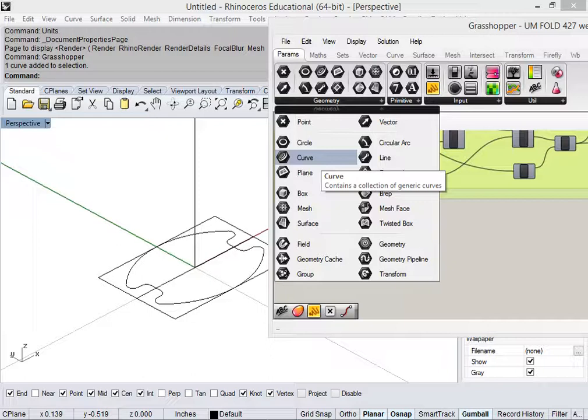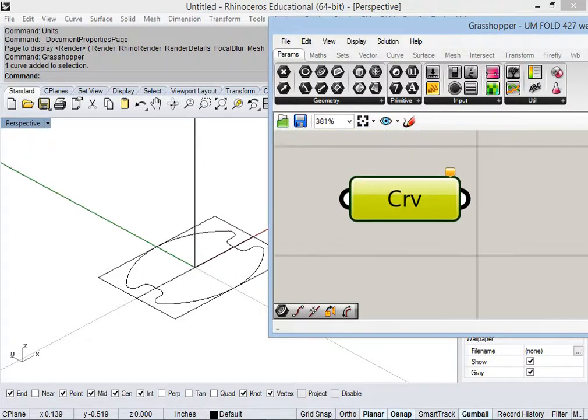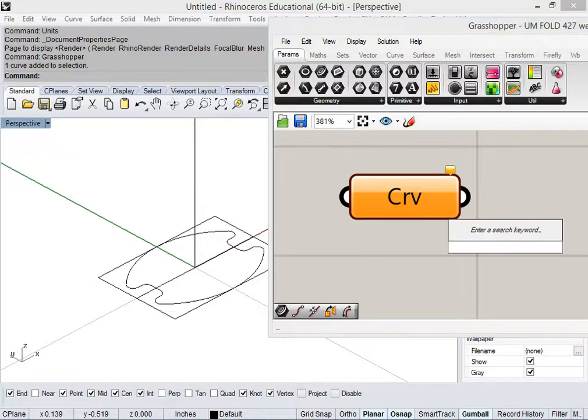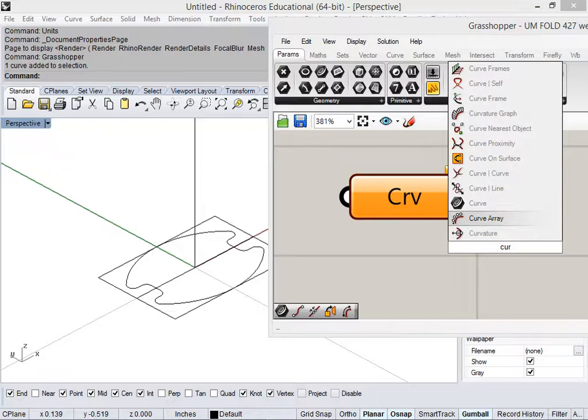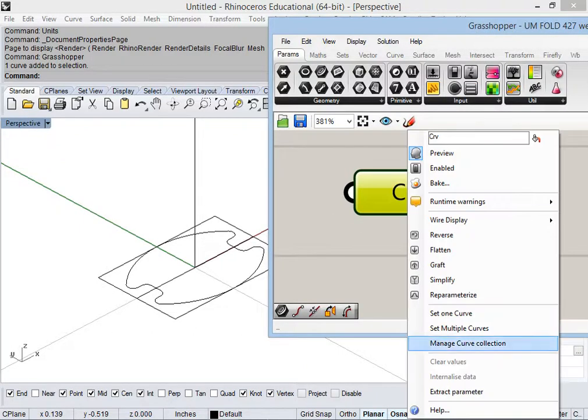When I talk about 2D, a curve is what you want to use. So you make this little thing here. It's curve, or you double click and type in curve. Then you right click and say set one curve. So basically what this allows us to do...